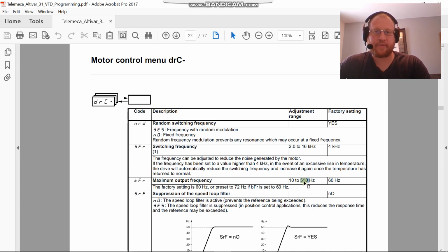Now, we know how frequency affects a motor, in that the higher the frequency, the higher the speed the motor goes. It's a formula that you should have learned and reviewed by now. So we can simulate a waveform up to 500 hertz. Now you'd need a pretty special motor in order to do that. Whenever we run a motor above its rated frequency, we say that that is a constant horsepower mode, which we're going to look at in one of the lectures. Factory default is 60.